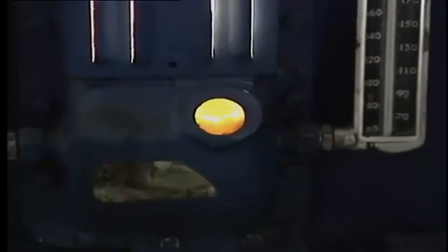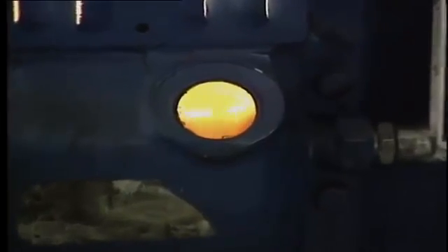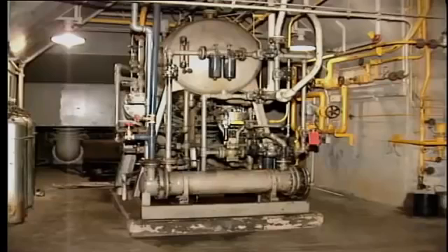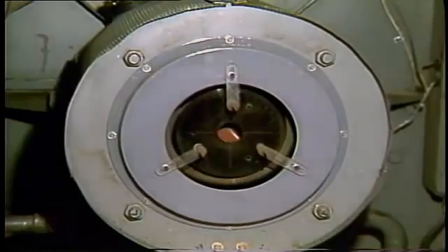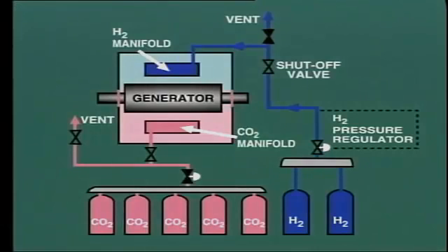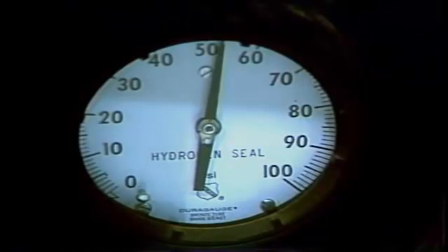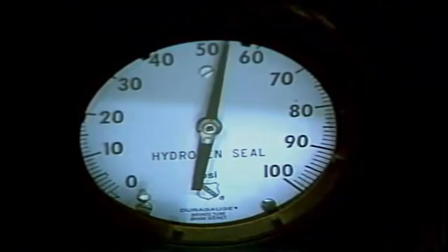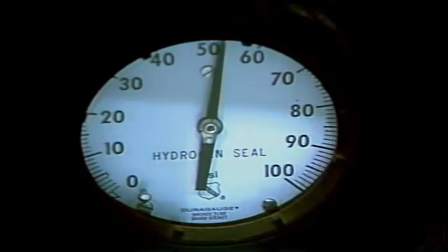This entails running a low-pressure oil pump to circulate oil through all of the turbine and generator bearings and starting the hydrogen seal oil system. The turning gear motor can now be started to rotate the shaft at low speed, usually about 10 RPM. The procedure for charging the generator with hydrogen is detailed in the next module in this series. This maneuver takes several hours to complete, so it is clearly necessary to get an early start and plan the complete operation when returning a unit to service.